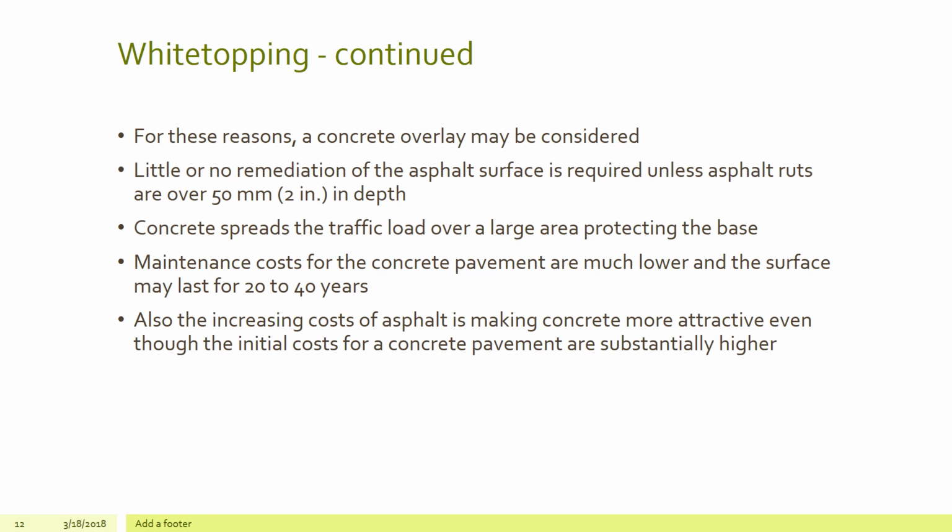Little or no remediation of the asphalt surface is required unless asphalt ruts are over 2 inches in depth. Concrete spreads the traffic load over a large area, protecting the base. Maintenance costs for concrete pavements are much lower, and the surface may last 20 to 40 years. Also, the increasing cost of asphalt is making concrete more attractive, even though the initial costs for the concrete pavement are substantially higher.